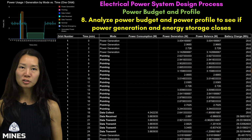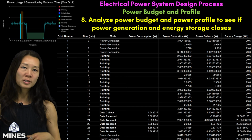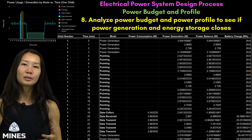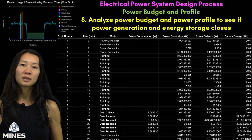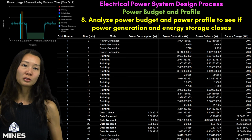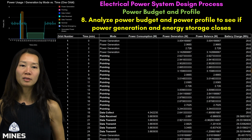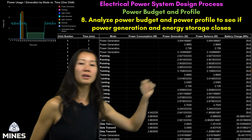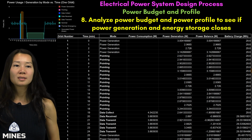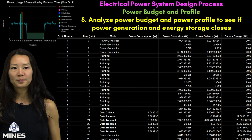If you don't have an energy storage solution, then you want to make sure that your power balance is always greater than 0, because you can't use more power than you can generate. If you do have an energy storage solution, you can draw some power from the battery to augment the power generation solution. You also want to keep track of the energy storage capacity over time. Here in this table, it is the battery charge on the far right, which shows whether the system charges the battery, discharges it, or runs at equilibrium.